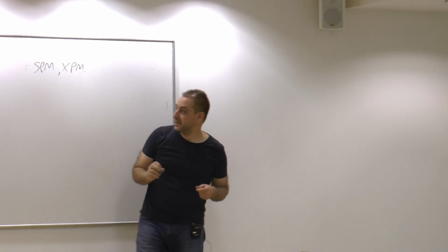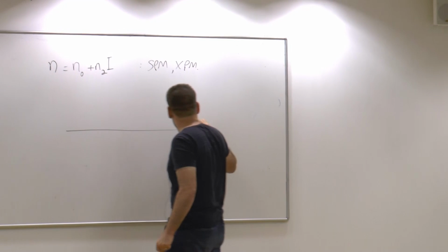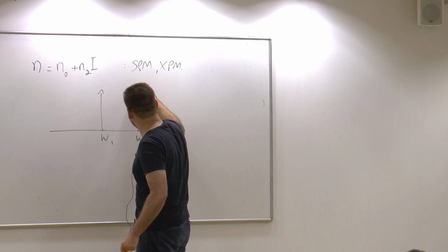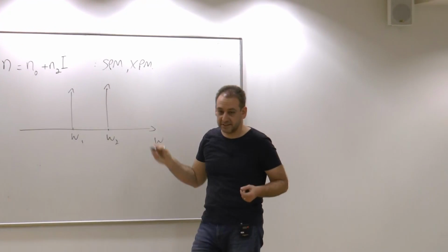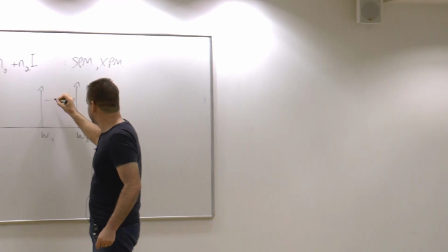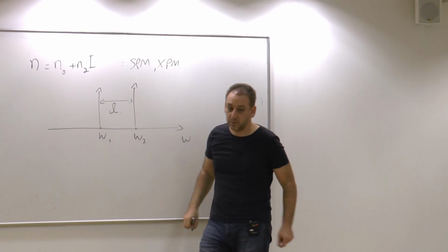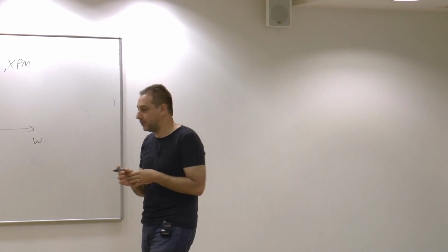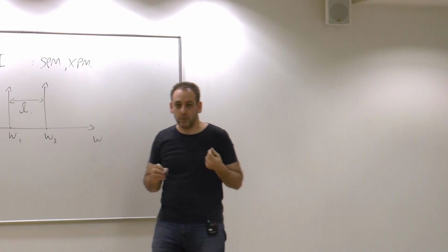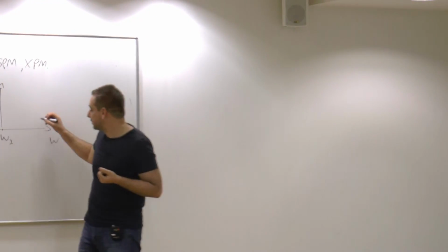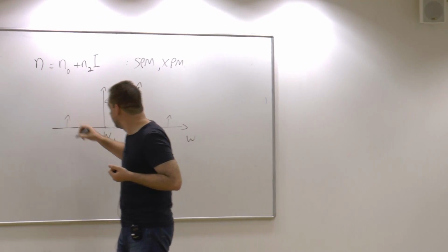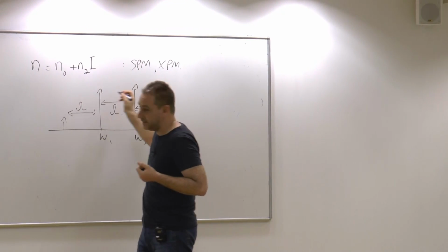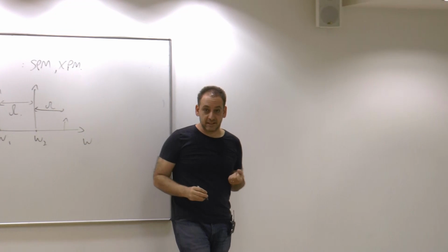One more thing we touched on is four-wave mixing behavior. When we launch in two signals, suppose they are continuous waves even, with some frequency separation between them that we know by capital omega, and we more or less showed, or I told you, that in nonlinear propagation we may encounter the generation of sidebands, or these satellite tones with equal spacing of capital omega above and below the incident signals.